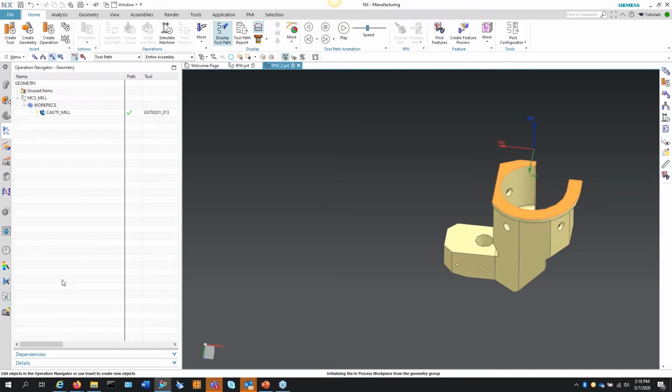It will put certain strategies in place for second operations, different strategies for third. So if you have it all in one operation, one program file, NX sees this as one push button start, and then it finishes that program. And you can tell it to do side 1 program folder, side 2 program folder, but that's just not the correct best practices of NX. So how would you do it in that way, or how do you flow the program correctly?